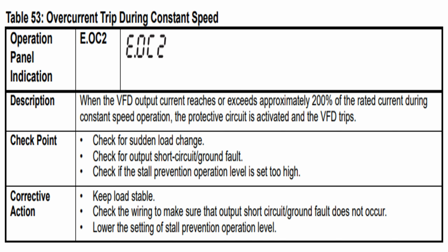Second reason could be that we have to check the output of the VFD, from the VFD to the motor. We have to check all outputs. And third, a very tight chain, gearbox, or belt, whatever we have on the motor, that is very tight, it also could be the reason. So we have to check all 3 and 4 parameters. If all is fine and it is still occurring, then there would be chances of a short circuit, or the power card of the VFD is damaged.